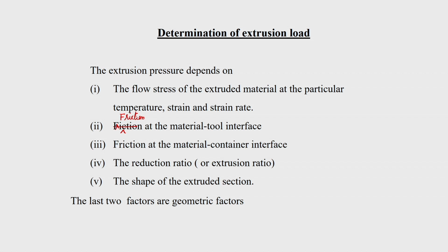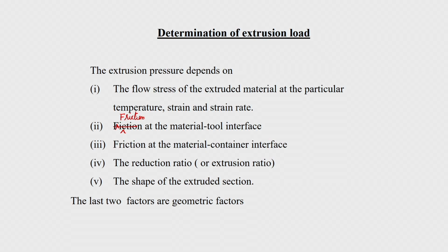Then there is the amount of reduction. Normally in extrusion we do not use the word reduction ratio, rather we use the word extrusion ratio. But ultimately these two are related, so in a way we can say what the reduction ratio is. The extrusion pressure depends on it: the higher the reduction ratio, the higher the extrusion pressure required, because internal shearing, everything will come into picture.